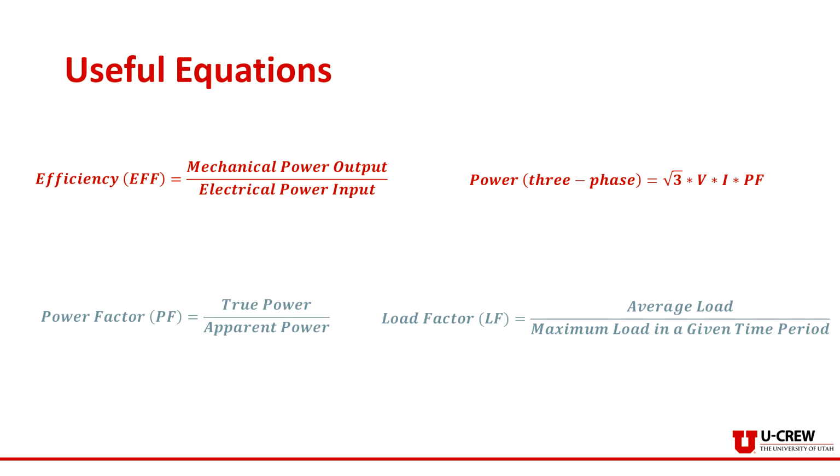You've already seen these now, but it's worth reiterating that the power factor is the true power divided by the apparent power, or otherwise the amount of power that you're actually paying for. And the load factor is the average load divided by the maximum load.